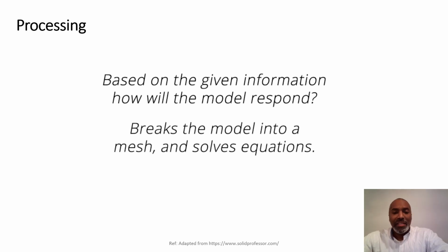So this next processing step really is the meat of the matter. This is where we actually solve the problem. Given the information we have about the model, we're trying to figure out how it responds. So every time you hit that solve button or run or go button on a software finite element package, just don't forget that what it's doing behind the scenes is breaking the model into a mesh. A mesh just means that it's discretizing, or breaking up the solid geometry, into lots of smaller pieces.